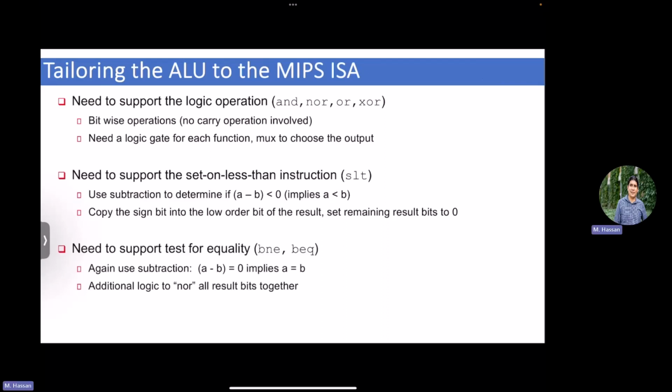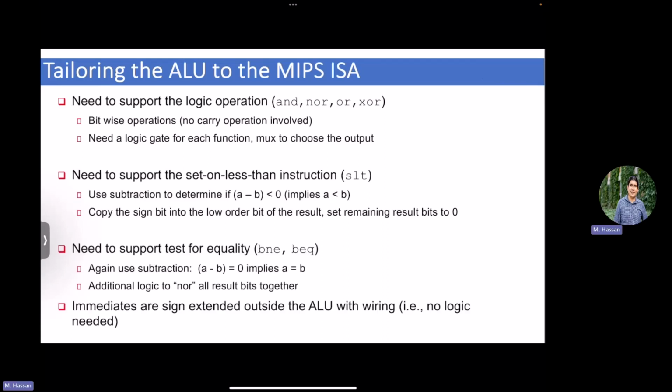Okay, I guess all of this is a bit of a detailed discussion that we can skip because it's specific to MIPS. Shift operations are a type of operation that we didn't discuss, but it's a bit straightforward. Shift is simply logic. It's one of the easiest operations to support in terms of hardware. For that reason, sometimes people try to optimize even multiplication and division with shift operations, right? So for example, if I'm multiplying by 2, how can I represent it using a shift operation? Shift left by 1 bit, right? If I'm dividing by 2, shift right by 1, right?